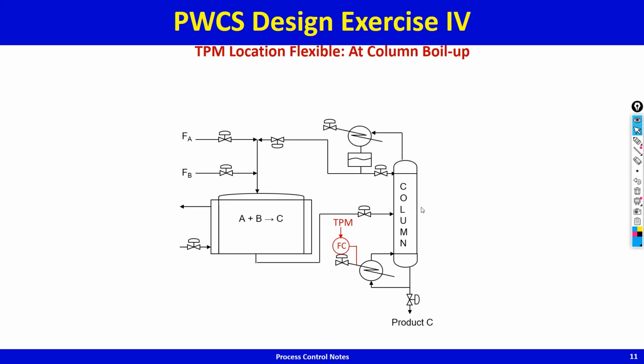And so what is typically done is you hold the pressure drop across the column at a maximum value so that the pressure drop limits the boil up.